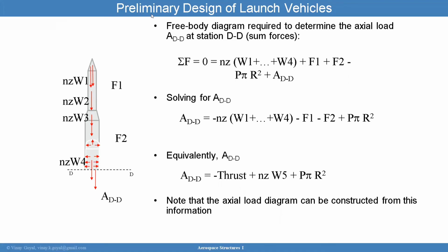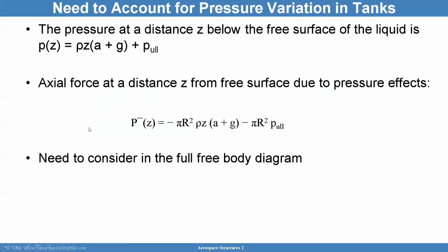And please pause. Sorry about that. And so I can construct the axial load diagram based on this information from tip to the very end. You have to do several cuts everywhere you can find and then do the axial load diagram, which is going to play a big role when you try to do structural qualification. Because, for example, I can do a cut here, and at that cut, I'll get an axial load, a shear load, and a bending moment. And all those three need to be used later for designing.